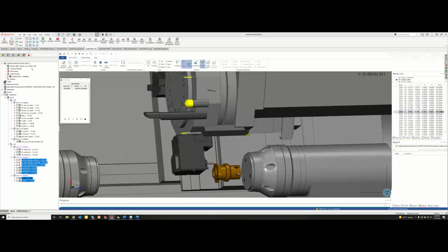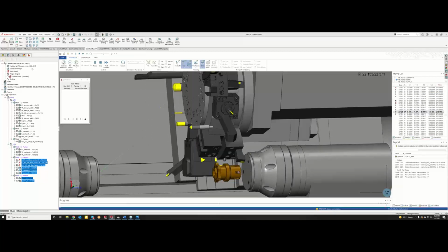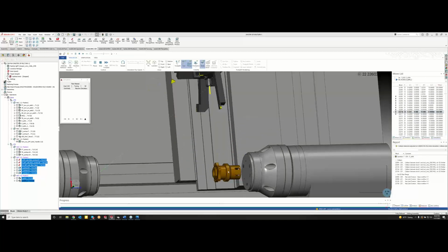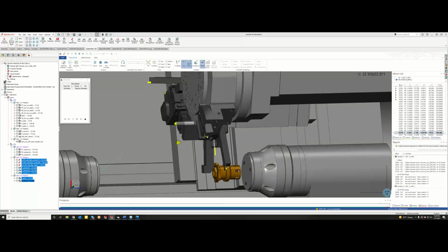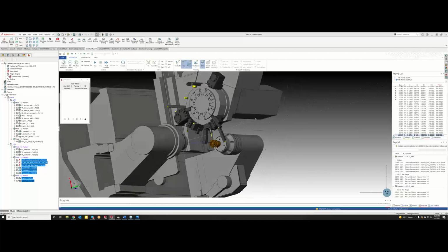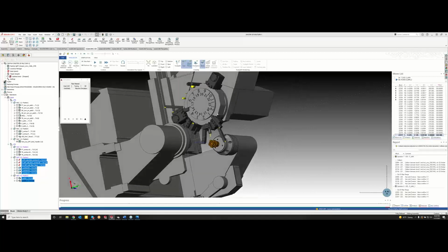I mean, obviously, if we have a 1/4 inch chamfer, oh, we got a crash here. What are we doing here? So that crash that was just shown there is actually a tool holder hitting our hex right here. So if we zoom out a little bit and rotate, you'll see I still have a lot of open spots over here.